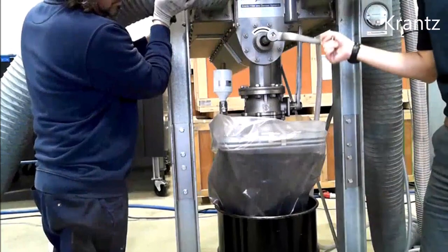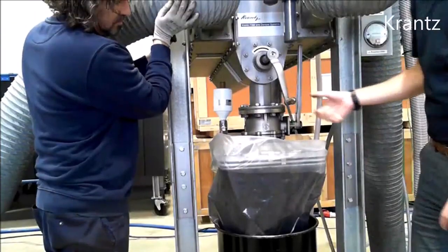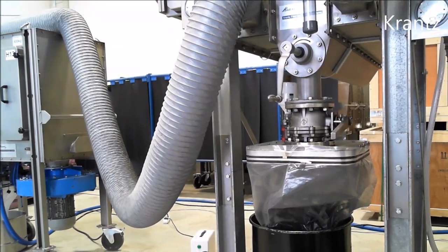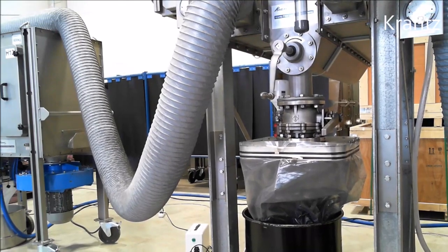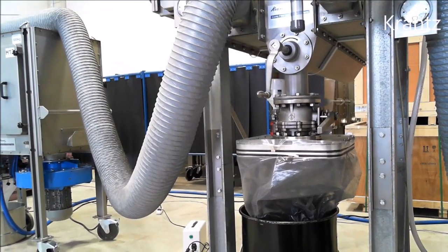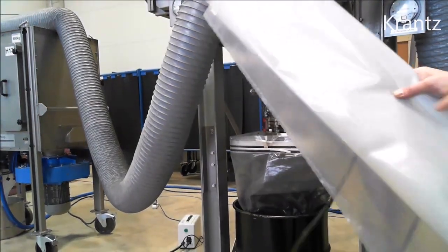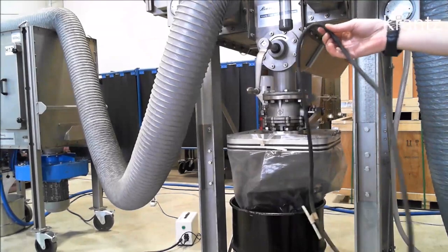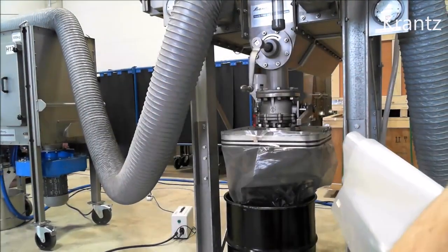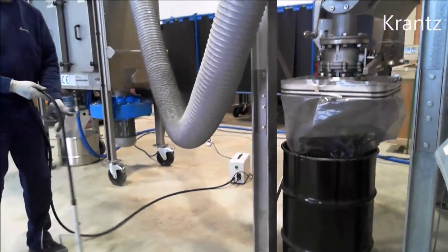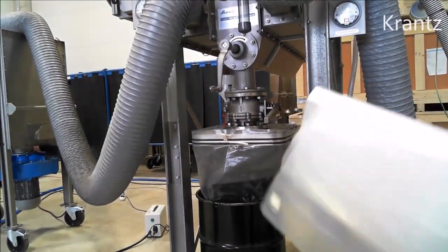And with this hand crank, it is also easy to control the amount of carbon that we are getting out. So we have now drained the carbon into the barrel, and now we want to change the maintenance bag so that we are able to fill another barrel. Therefore, we need one new maintenance bag, one new rubber ring, and a clamping device to clamp the bag and a heat seal device. And now we will show you the procedure how to change the bag.